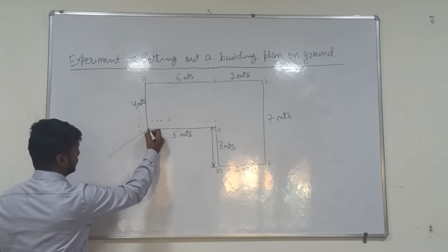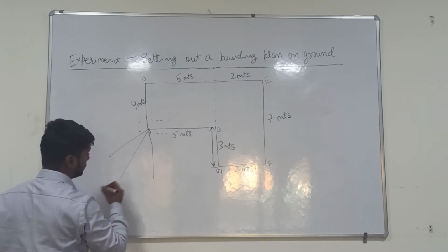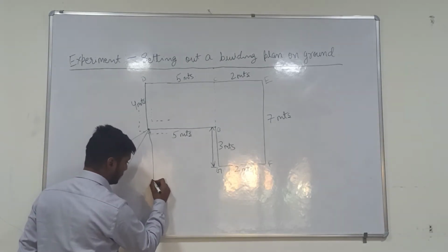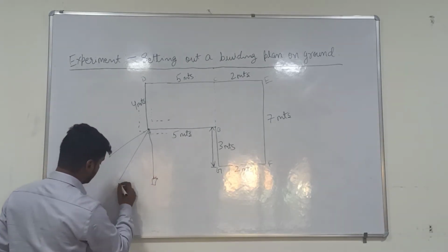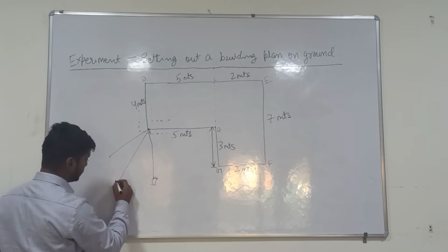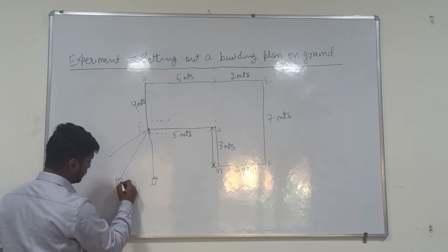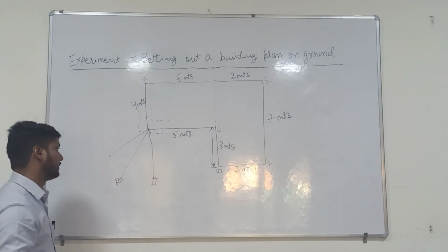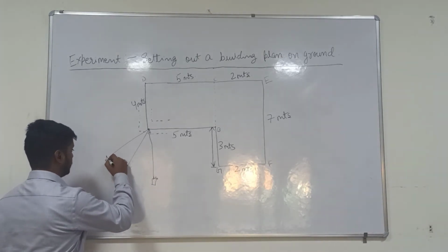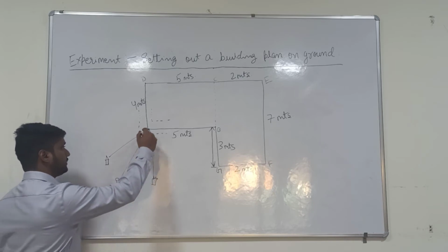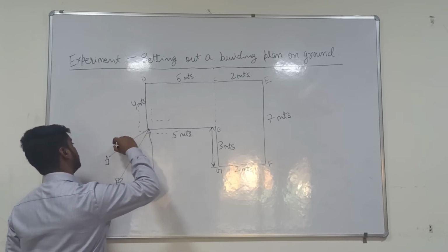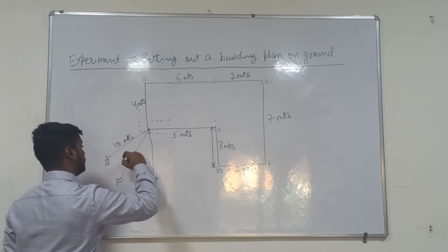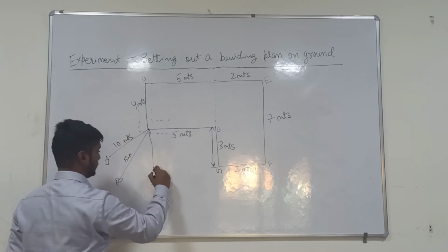and we have to take the distance from 3 different permanent points whose positions are already known to you. That permanent point might be a building, or a structure which is immovable. Of course you cannot take vegetation, because vegetation is not considered a permanent object. So let's say you have taken the distance of point A from 3 different permanent points to be 10 meters, 15 meters and 12 meters in this case.